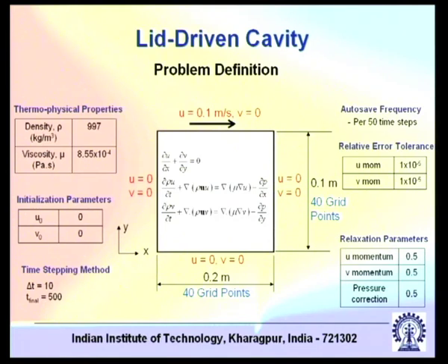Say you have a boundary layer flow. When you have a boundary layer flow, you need to capture the strong gradients of velocity and temperature, or whatever, depending on what type of boundary layer it is, within the boundary layer. To do that you need a large number of grid points within the boundary layer, at least a substantial number of grid points. If your gridding is such that you do not have any grid point within the boundary layer, say one is at the boundary and the next one is outside the boundary layer, then you are not able to capture the physics within the boundary layer.